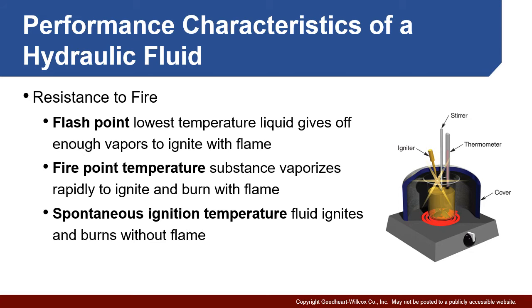So in general, even in a hydraulic fluid that we're trying to be careful with, there's going to be a certain amount of vapor, particularly in any kind of open container with it. In those situations, the flash point is the lowest temperature at which those vapors will ignite, but you need exposure of flame. And it's called the flash point because in general, the vapors will ignite and burn off, and then the fire would go out.